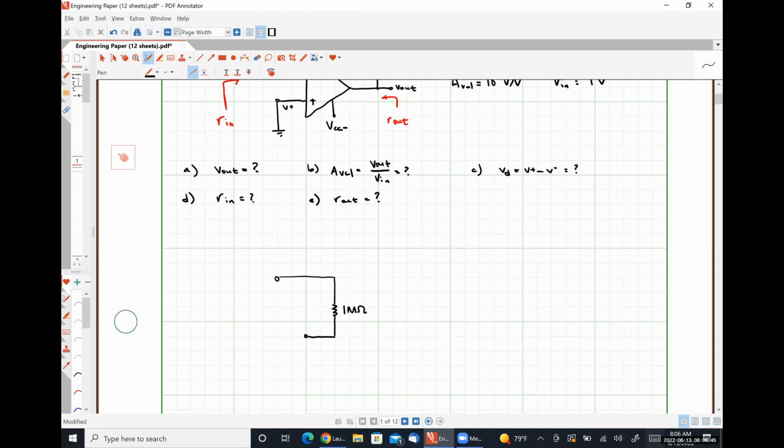For this particular circuit, and really anytime I have negative feedback, I tend to place the non-inverting input terminal on bottom and the inverting input terminal on top, just to make the circuit easier to draw with our feedback network. So that's going to make our differential voltage VD have positive polarity on bottom, which is opposite what we would usually have.